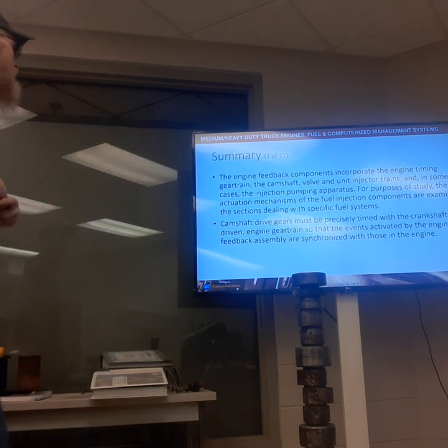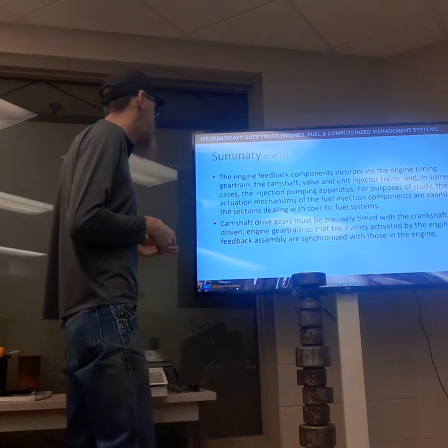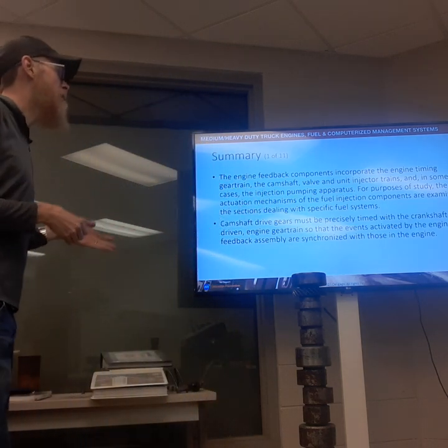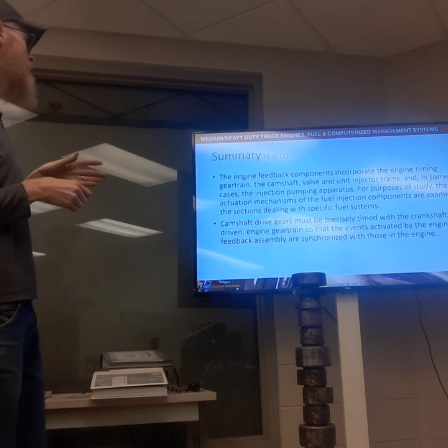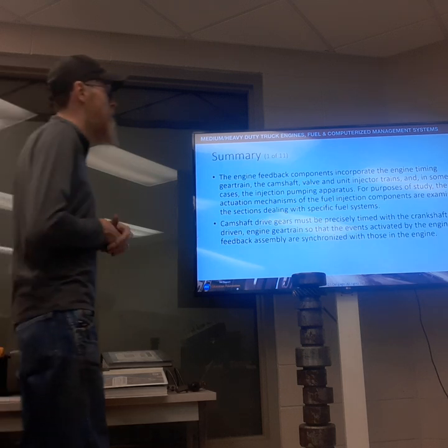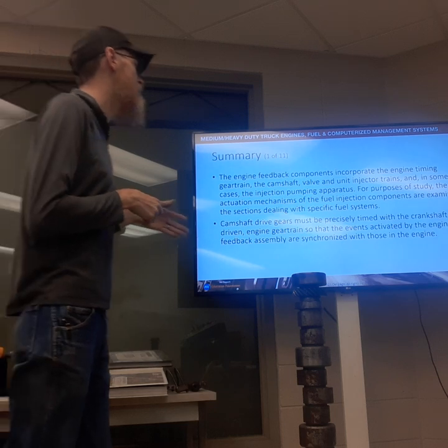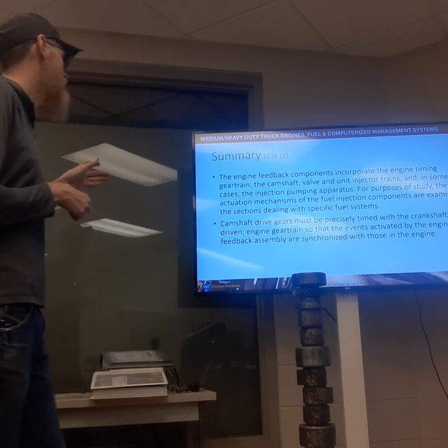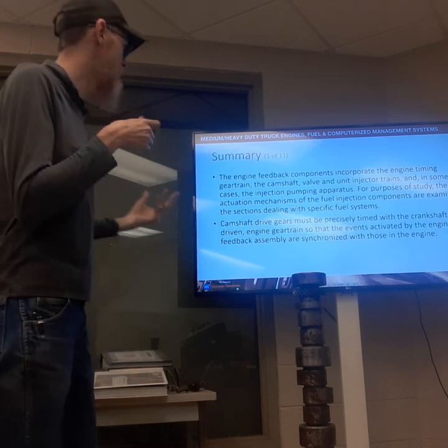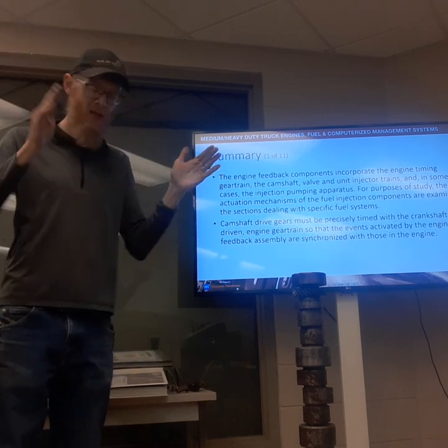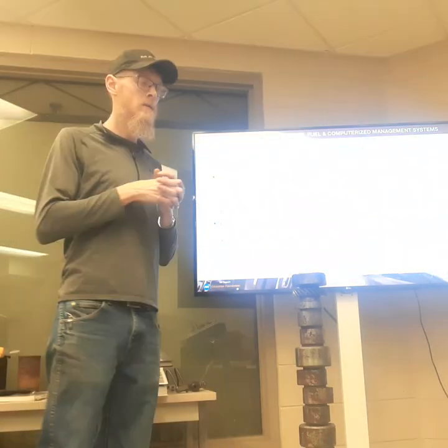The engine feedback components incorporate the engine timing gear train, the camshaft, valve and unit injector trains, and in some cases the injection pumping apparatus, so fuel pump. For purposes of study, the actuation mechanisms of the fuel injection components are examined in the sections dealing with specific fuel systems. So again, it's been hard to condense diesel engines down into two days worth of lecture time.